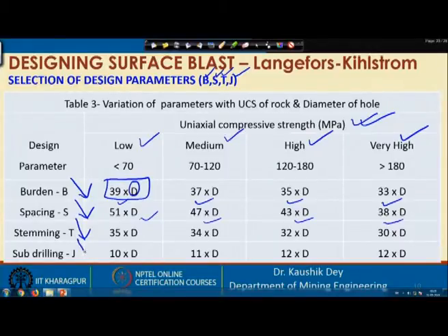Subdrilling length is basically increasing with the increase in the strength of the rock: 10, 11, 12, 12. So, we need more subdrilling if the rock strength is high.